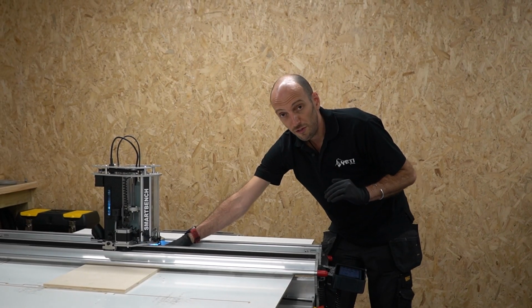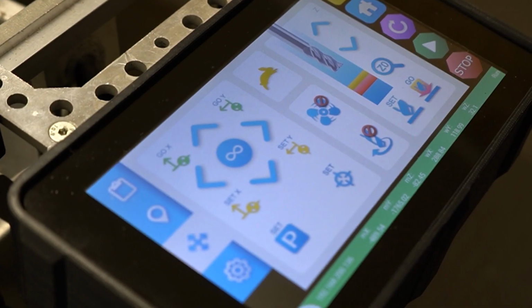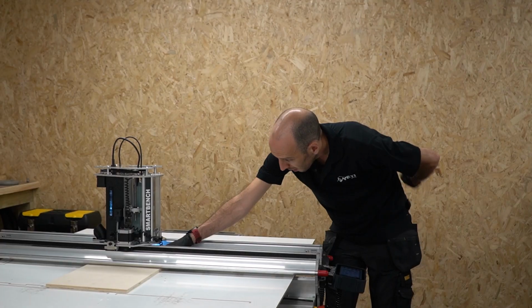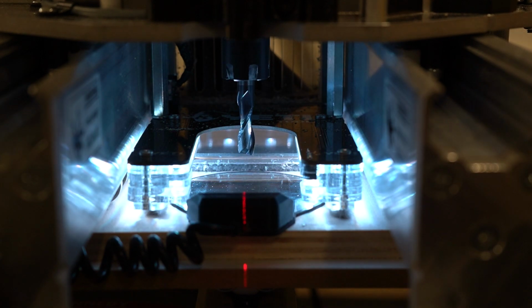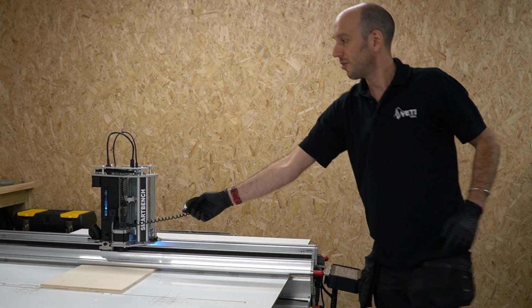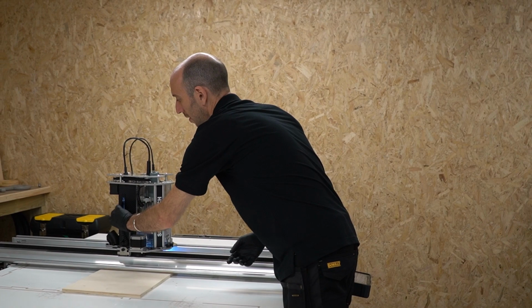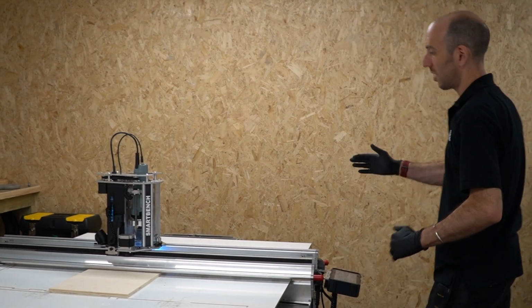When it's close enough, I'll then press the Z0 Pro button, and you'll see the tool automatically lower towards the Pro plate. On registration, you'll see the dust shoe flash green, telling you that it's saved its working datum.